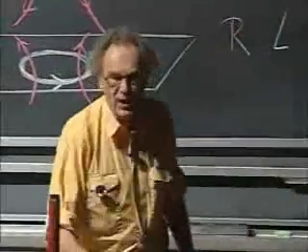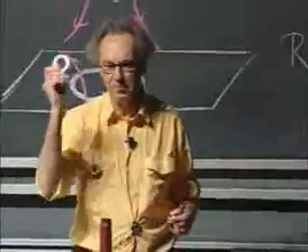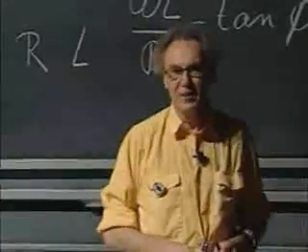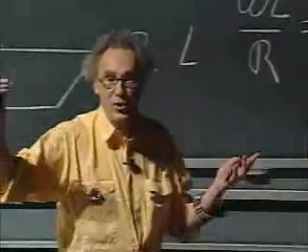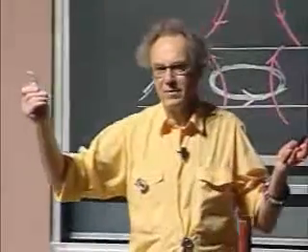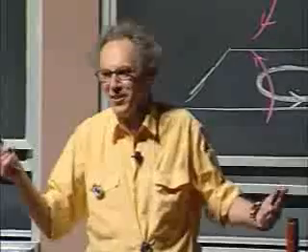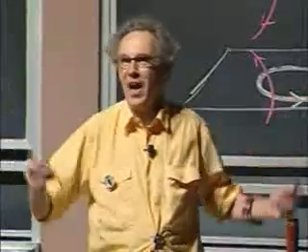I have another ring here which has a slot, also aluminum. Same ring, but it has a slot. Well, the EMF in this ring is going to be identical. There's no difference. In fact, the self-inductance of this ring is identical. But the resistance of this ring is huge, because there's a slot in there. The resistance is almost infinitely high.